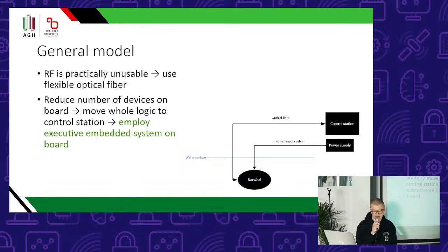So we need another computer on board of the robot actually, because we need to receive the packets and then convert the bits in the packet to actual electrical signals that control motors or servos or other stuff. But the problem with the computer on board is that it takes space, and we have very limited space on board because we have just one box or one tube on our robot. We want it to be small and light.